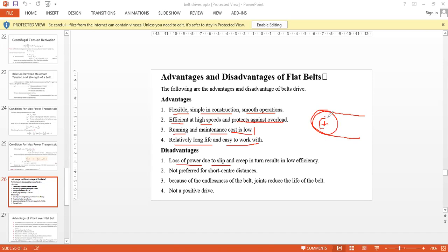The pulley is going to rotate in this particular direction. If the belt is not at the required tension, if the belt is too loose, then even though the driving shaft is going to rotate, at the driven end the belt will not move at all, because it is too loose. It will just slip in the area of contact because there is not enough tension.